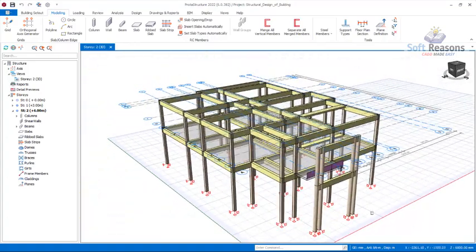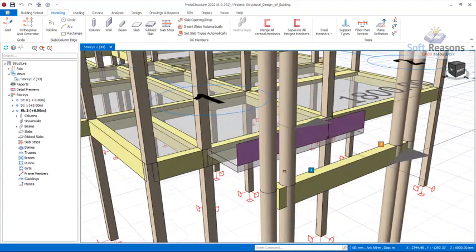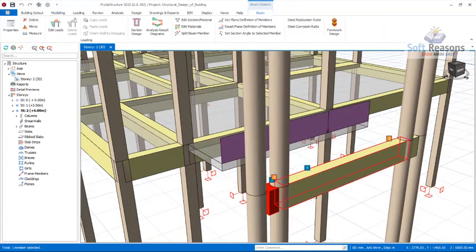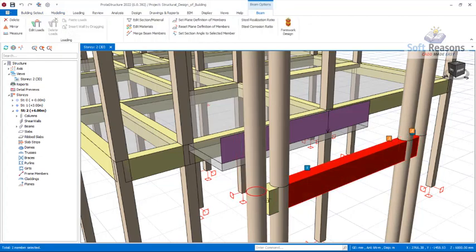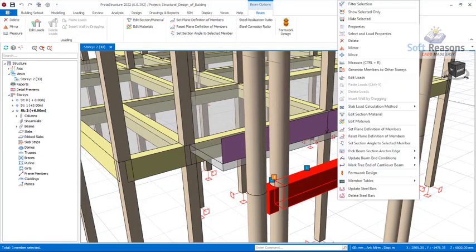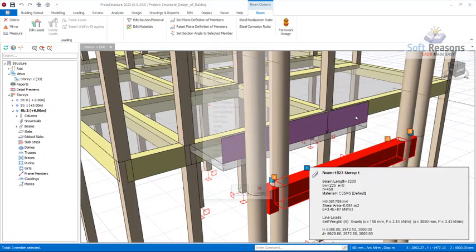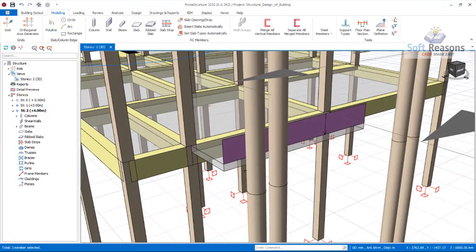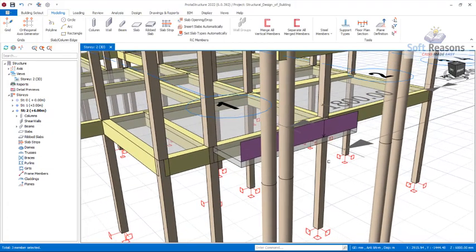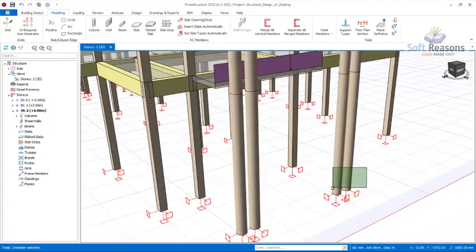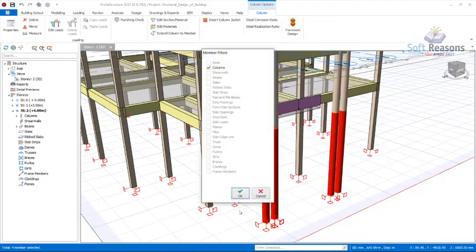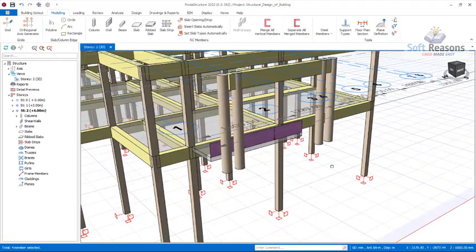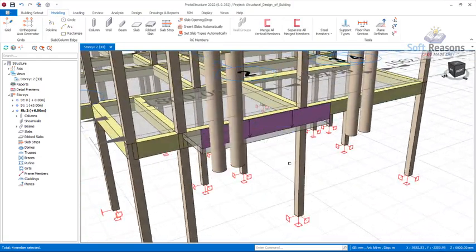Alright, so we are now going to work on these reinforced concrete columns. As I said earlier, we wouldn't have beams here. We don't need to have RC beam, so just delete that. Okay, options. And also this column is a slender column, so we will actually get rid of the first floor of that column. So this one now we will make it slender.